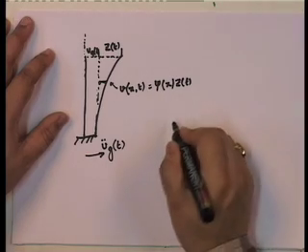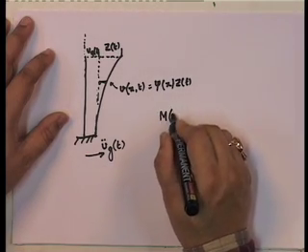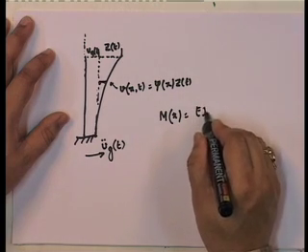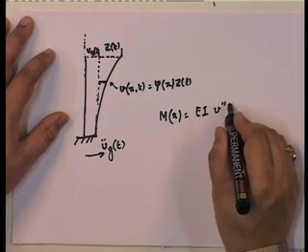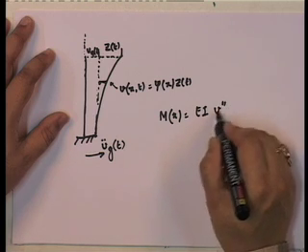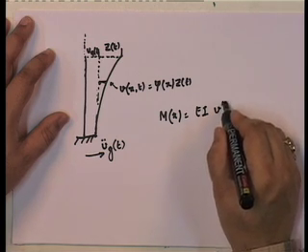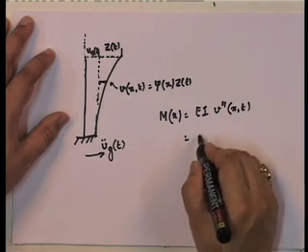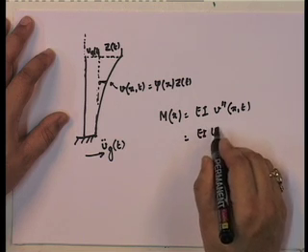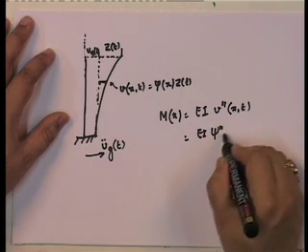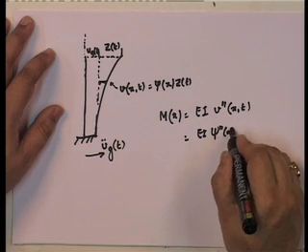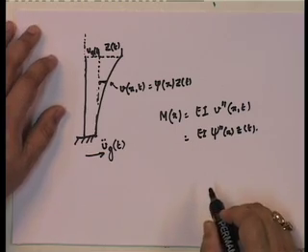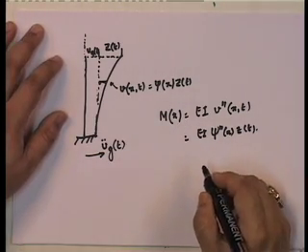So, therefore, the m x due to the deformation is equal to E I v double prime, which is d squared v by dx squared, we call it as v x double prime. So, this is equal to E I into the second derivative of xi x into z of t. So, this is my m x due to the deformation.